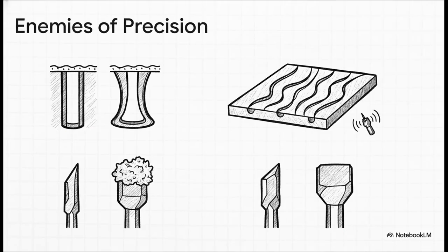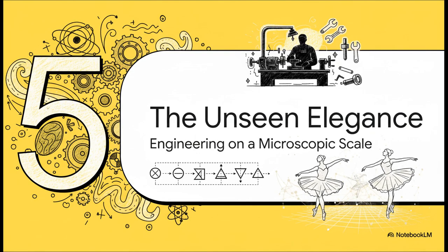And even when they've nailed the speeds and feeds, machinists are in this constant war against the enemies of precision. They're fighting things like bell-mouthed holes, where the entry to the hole gets flared out. They're battling chatter marks, which are literally the pattern of vibration carved right into the surface, all while keeping an eye on the cutting tool itself, watching for wear that could ruin the part.